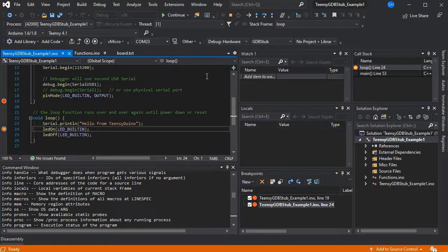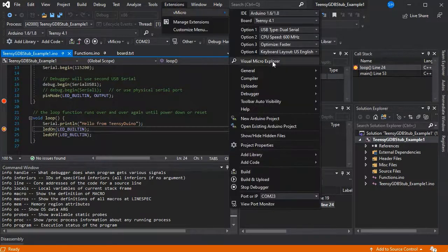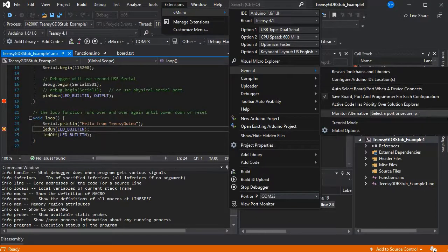So if we now attach, we can step, and then when we stop it will run our additional command just before it runs the final quit. So that can be useful if you need to run a monitor exit command, for example, or it depends which debugger you've got as to what you may need to run.